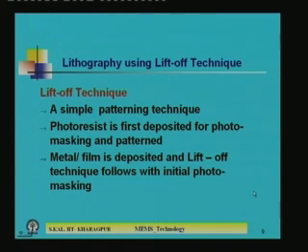Now, there is another kind of photolithography technique which is known as the lift off technique. The lift off technique is a special technique where you do not require the etching solution of the film. In some cases we may not know the etching solution. For example, if you are going to pattern a tungsten film or molybdenum film or some other ceramic film whose etching solution is not known, but you want to pattern it. In that case the ideal technique is the lift off technique, which is totally different.